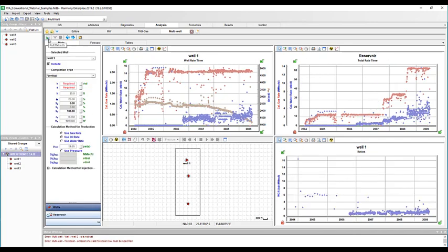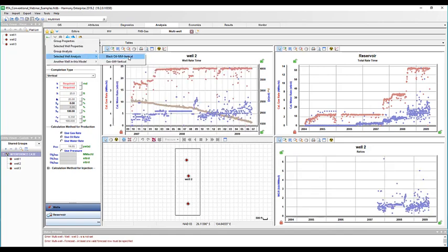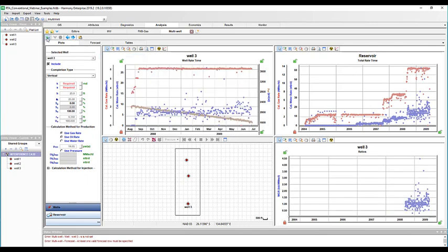Now it's really easy to seed in the parameters for each of your wells. I can simply seed in my parameters from my numerical models that I've just created for each of my wells, and this will seed in my permeability values, skin values, and saturations. Now, if we remember, the numerical model is a multi-phase model, so it takes into account those changing relative permeability curves, saturations, and PVT properties.